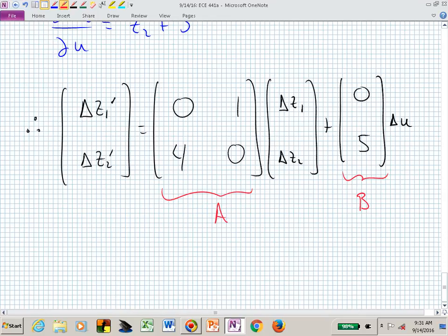What if the equilibrium condition that we were linearizing about was upright vertical, and now you tap it? Now it's not going to go back to that equilibrium point, is it? That would be an unstable equilibrium condition. The downward would be a stable equilibrium condition. We want to see, after we've linearized this second-order nonlinear system, what are the natural dynamics around this nominal operating condition of 0, 0, 0? How can we find that?